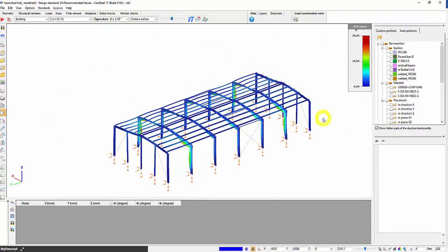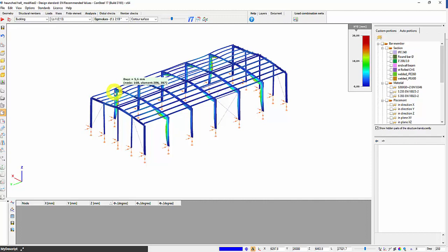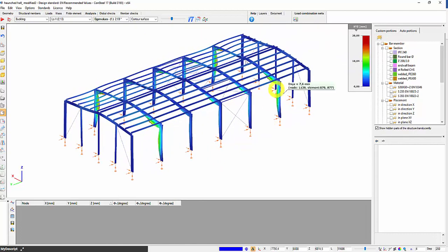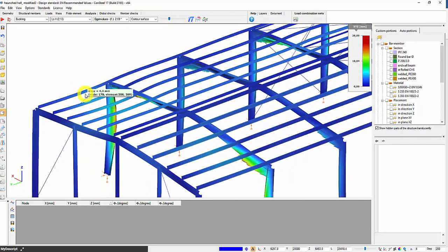So, on the one hand, their stiffness appears with half cross-section in the stiffness matrix, so these end walls won't lean out, the bracing will work. On the other hand, they are excluded from the geometry matrix, so stability analysis is not relevant to them. Thus, the actual stability analysis is performed, and in this case, it can be seen that the usual lateral torsional buckling shape of the frames will be dominant at a significantly higher, already acceptable critical load level.